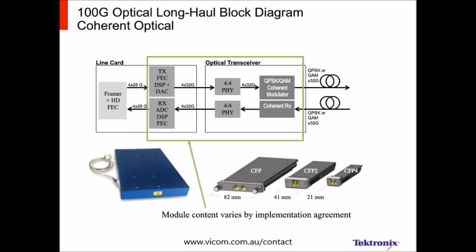Now, as we move from the 5x7-inch module to some of these smaller modules, as the OIF is doing, we don't necessarily have the same dividing line. For example, there's a CFP version that I'll mention in a second that does include all of this just as the 5x7-inch module did. But now we're seeing this with the CFP2 ACO project at OIF, the dividing line moving to in between here, so that the really expensive, important ASIC that does the processing both on the transmit and the receive side can be pushed out of the module, thereby reducing its power dissipation and making things more flexible for implementation. So there's still an argument, okay, what's better, putting the ASIC inside the module or outside the module, but there's no questioning the fact that it certainly makes this module smaller and consume less power if you push the ASIC outside of the module.